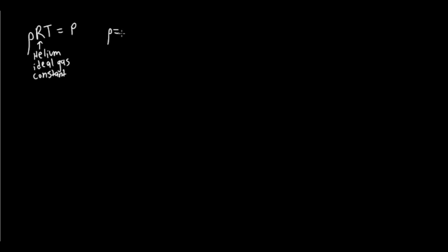And we will get rho is equal to P over R T, where P is the pressure where the helium is existing, so 25 psia, and T is temperature in absolute, so Kelvin or Rankine. In this case, we're dealing with Rankine. So we're going to do 3600, because again, we need to put this in standardized units, PSF. It's kind of assumed that it's absolute.